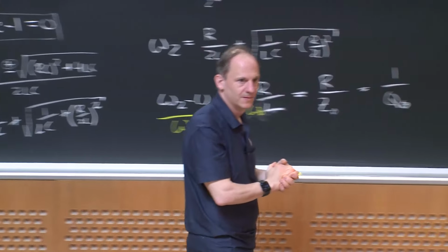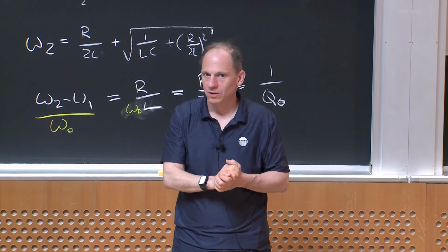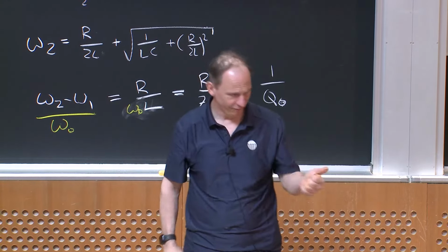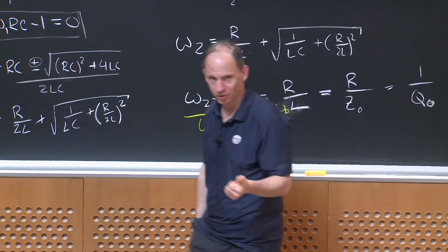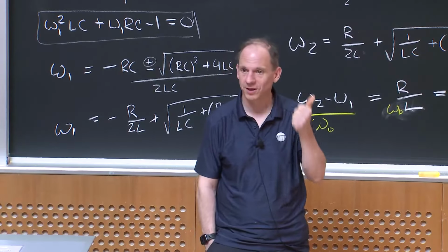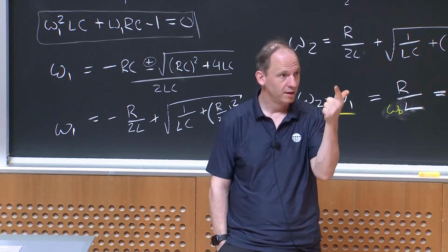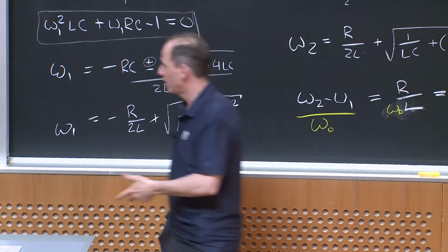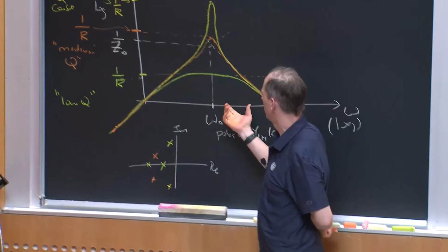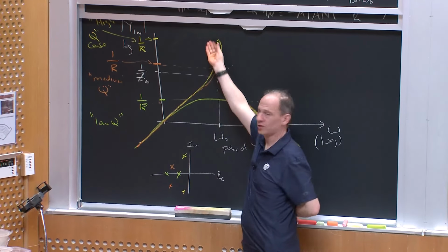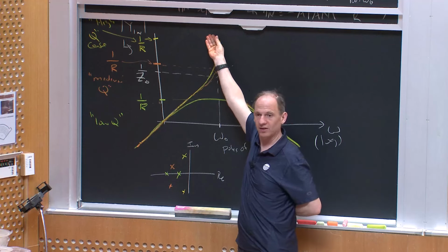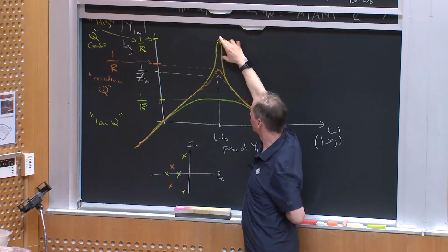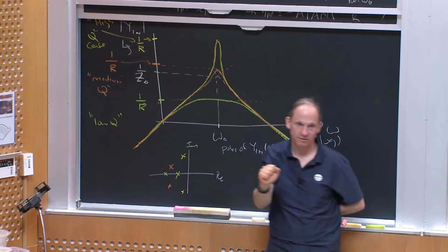Questions about that? So what I want you to take away from today, and this is just done in the example of a series resonant circuit: first of all, when you're handed a circuit like this and you're thinking about sinusoidal drive, you want to calculate characteristic impedance and natural resonant frequency. The next thing you want to get after that is quality factor, Q naught, of the circuit, because those are going to tell you essentially how peaky or sharp this whole thing is. The second thing we can take away is what kind of bandwidths I need to operate to modulate power, and what kind of stress ranges I am going to get compared to my input drive in the network.